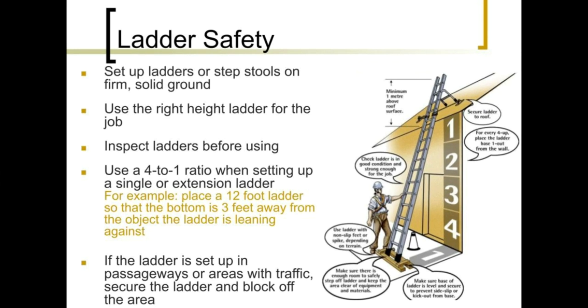Lots of notes here on ladder safety. Set up ladders or step stools on firm, solid ground. Use the right height ladder for the job. Inspect ladders before using. Part of making sure that it is the right height is making sure that the ladder extends over the top of the surface that you're wanting to get onto.